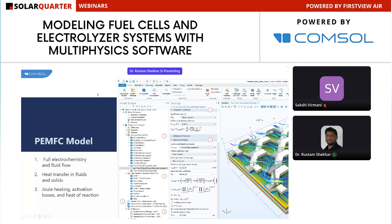So how will that look in the COMSOL interface? This interface we saw earlier as well. We can see the full electrochemistry has been modeled. We can see the full flow and heat transfer has been modeled, and then the coupling between the two has also been modeled by using the multiphysics node.